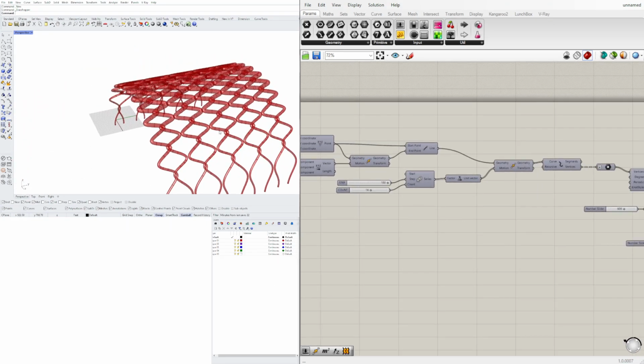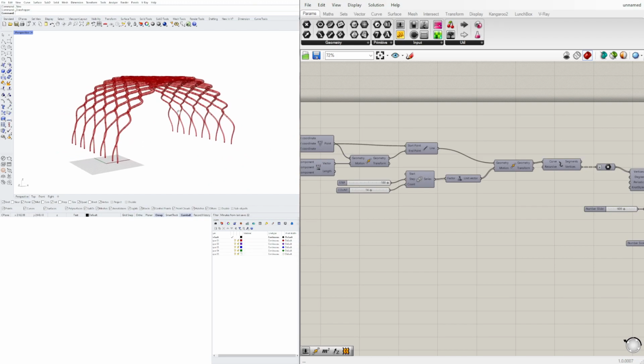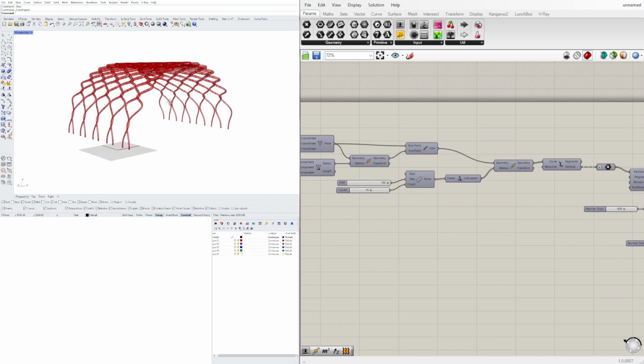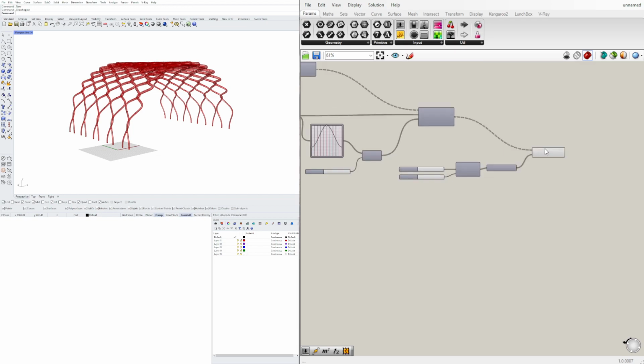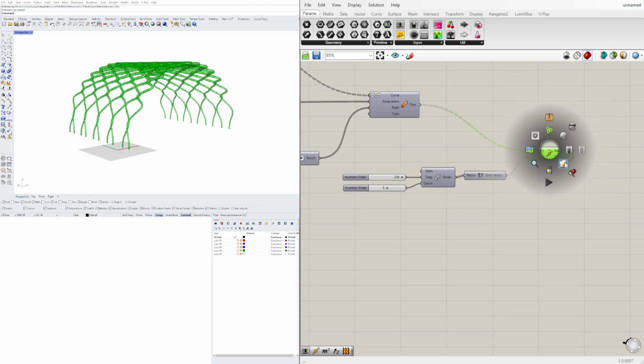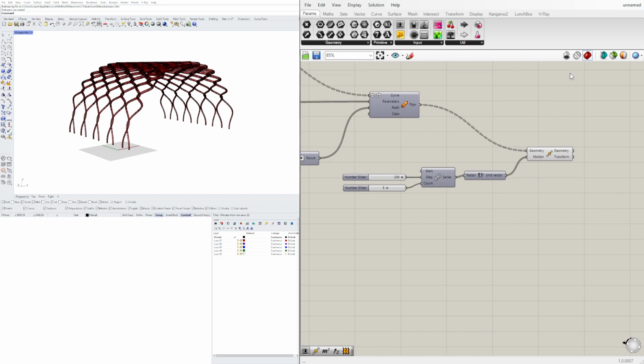Now with this, let's bake it and let's take a look what it looks like. So with this, we'll go here to our layers, layer 1 or the default layer, and I'll middle click and bake this. Now I'll disable the preview on it. And actually let me save it real quick and then we'll jump in and take a look at the baked version of it.